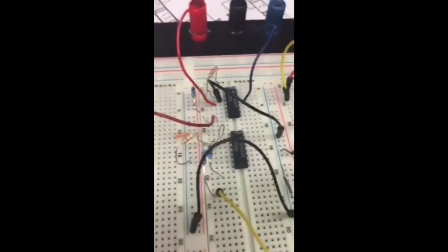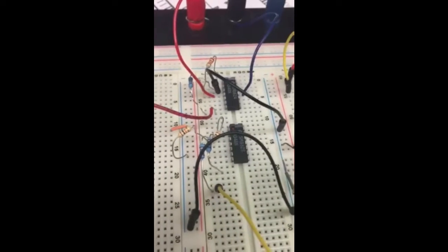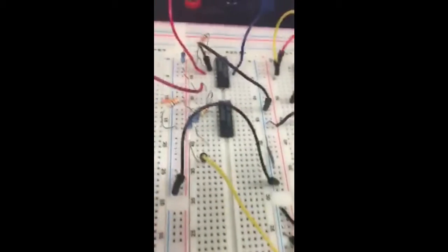We found common mode gain by connecting both input voltages, so having them from the same source. So this is the gain of my differential op amp. They intersect here, and this shows the phase of it. The magnitude can be found from this graph, and all of this is a function of frequency.